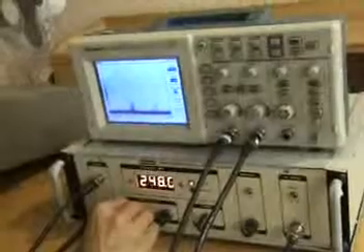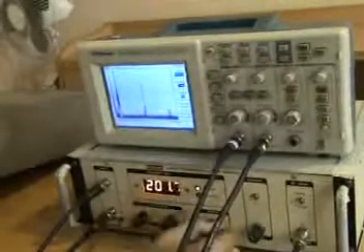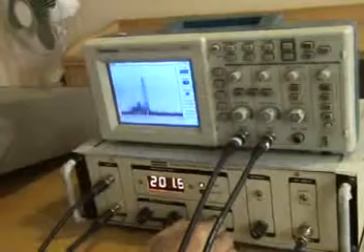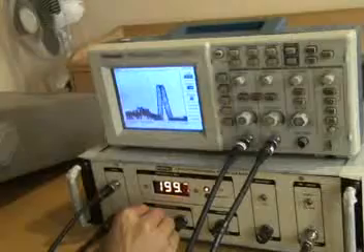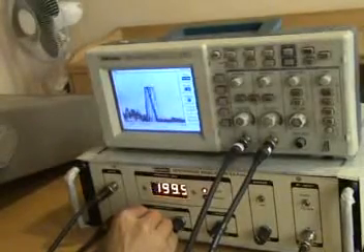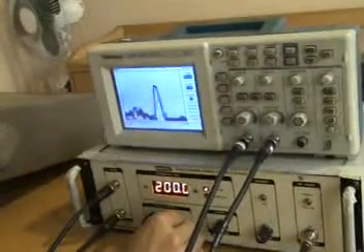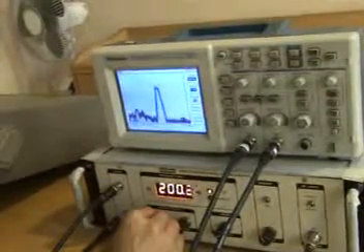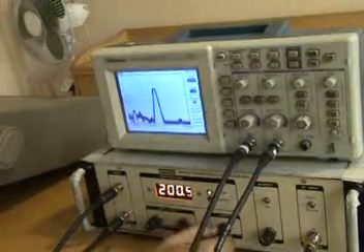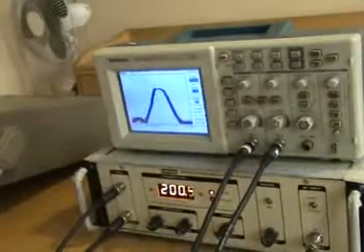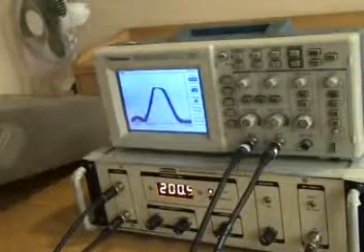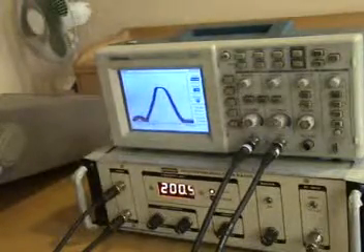Now if we were to see the signal once again at 200 megahertz, we'll bring this to 200 megahertz and decrease the sweep width. Always bring the signal to center frequency and then reduce the sweep width. In order to bring it precisely, use fine control pots. Now as you can see, the display accuracy is 0.1 megahertz or 100 kilohertz.